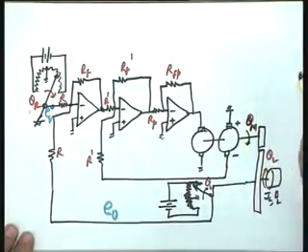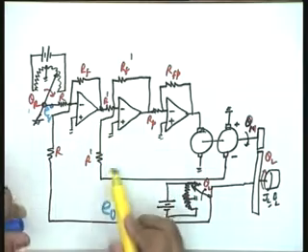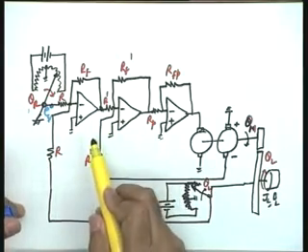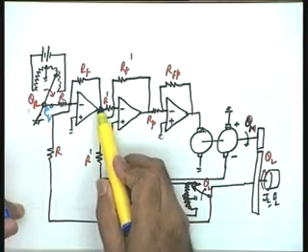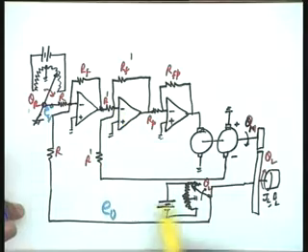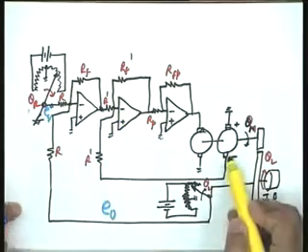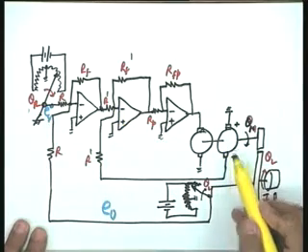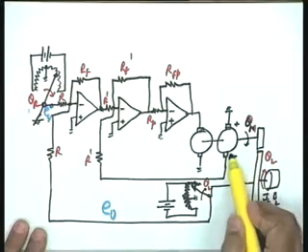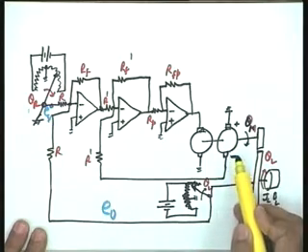Okay, let us go back to the diagram. So, I have reached this point. At this particular point, I have a signal ER minus E naught multiplied by a constant, that is the gain of this differential amplifier. Now, I need your attention at this point. What I am doing here is that in addition to this signal, I am taking another signal which is coming from a tacho generator. This tacho generator, again the signs, I need your attention on the signs also.